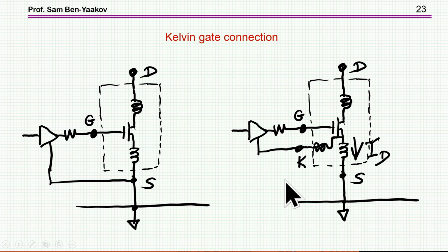The reason is that although we do have here also inductance, as we have here, there is no amplification here. That is, in this inductance, when you have a small current, the current here becomes much, much larger because here we have the current of the drain, while here we have only the current of the drive loop, and therefore, although it's adding inductance, it doesn't matter, but the effect is much, much smaller than this effect in which you have amplification.